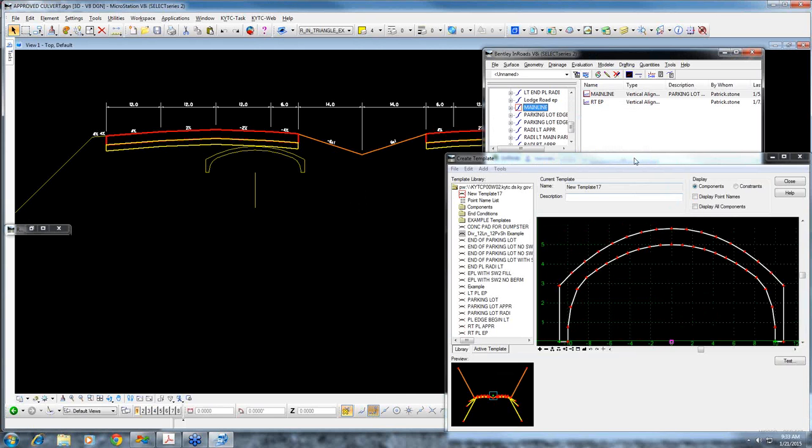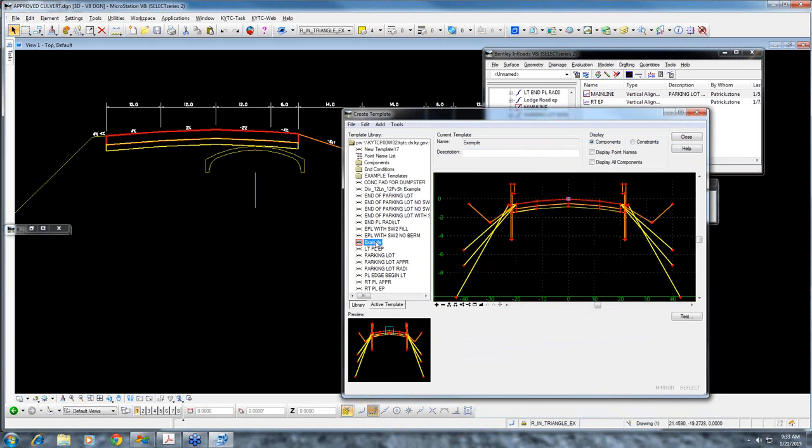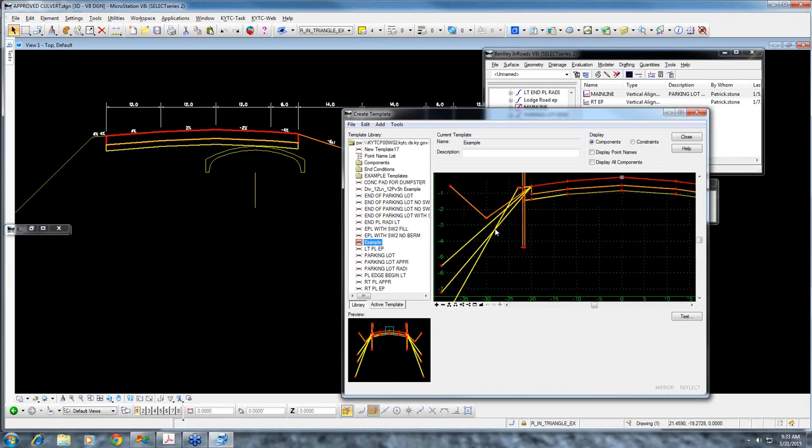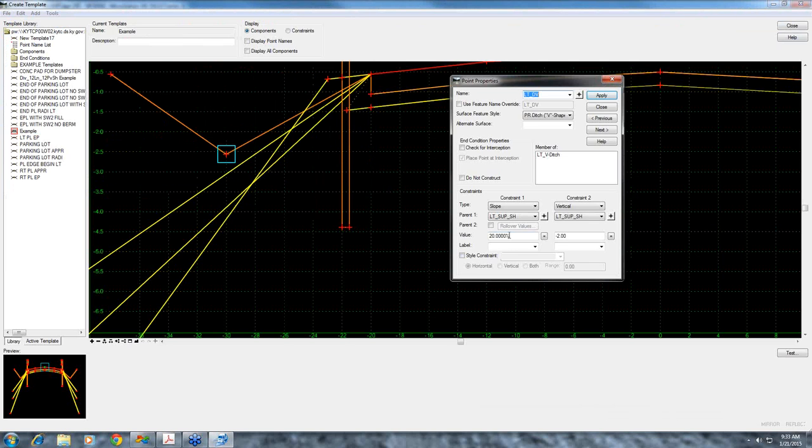Now, I want to show you too that those key ends that we were talking about earlier, you can go in and use any of the slope key ends that you want to. Like, for instance, this is set to 20%. If we wanted that ditch to be a 2-to-1 slope, if you hit a 1, 2, then you hit a tab, it changes it to the percent, and that's what this one uses. And it'll change that. You can use the percent.